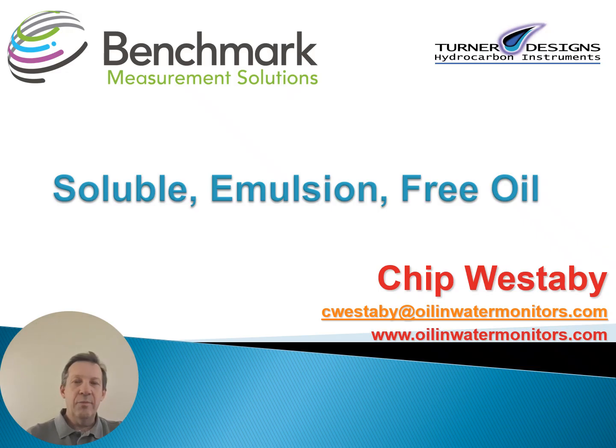Today's going to be a little bit of a different presentation than our normal micro application discussions. What we're going to talk about today is a presentation from a roundtable at the February Produced Water Society conference. Most industrial and produced water processes require oil measurement of water discharge. But the oil can be in different formats. It can be dissolved within the water. It can be a free oil droplet. It can be emulsified. There's different ways to describe how the oil and water mix together. And today we're going to talk about what those differences are, how to measure them, because defining what needs to be measured in the water is important to figure out the best method to do the measurement.